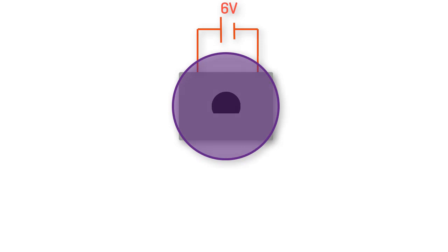Just to give an easy example, suppose I have attached a pulley to the shaft of the motor, and I've hung a weight from the pulley. So the motor has to exert a torque to lift up the mass, and we could figure out how much torque the motor would have to exert by multiplying the mass times the acceleration of gravity times the radius of this pulley. Whereas the motor speed is related to voltage, the motor torque is related to current.